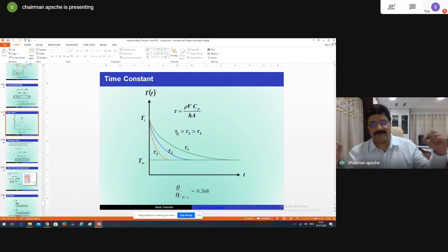Now, how is this EMF induced in the circuit? Not all pairs of metals can give it, only certain combinations work well for the Seebeck effect. So you choose two dissimilar metals formed into two junctions. The EMF induced in the circuit depends on the temperature difference between the hot and the cold junction. The hot junction is the point which is actually sensing the temperature of the fluid you are measuring.